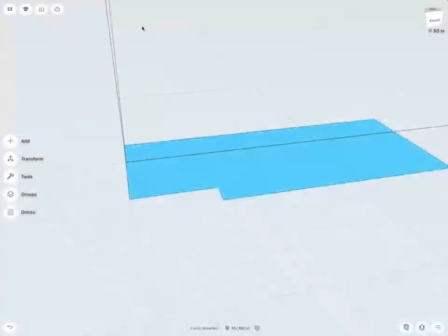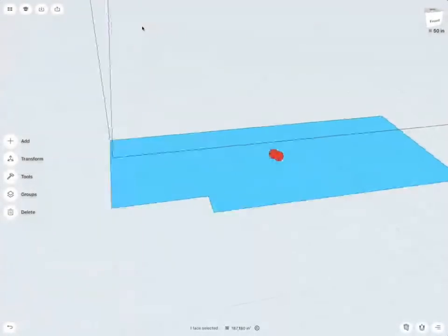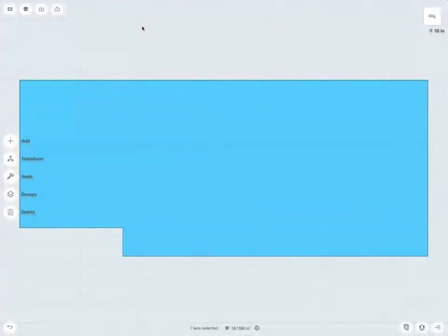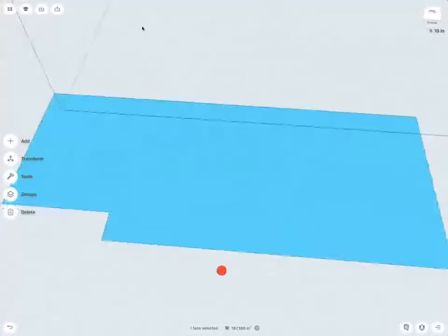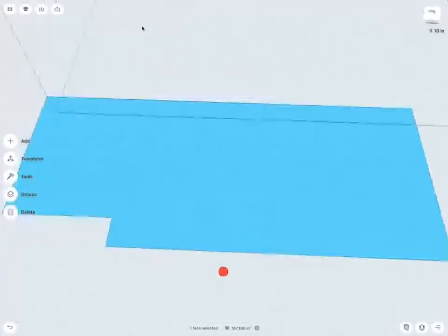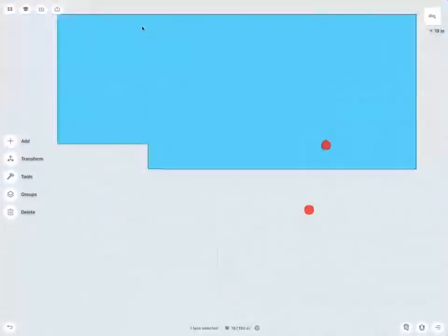Then with the pencil, you can select the plane or the profile, and then with a finger, double tap. That actually will, as you can see, rotate the camera perpendicular to the sketch. And if I now rotate, you see that the grid adjusted to there. Very nice.